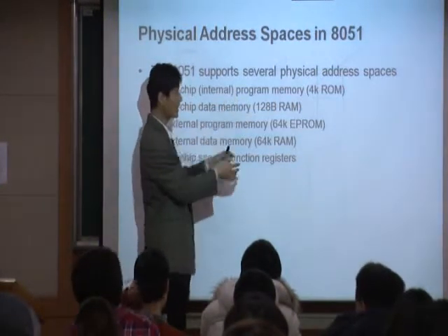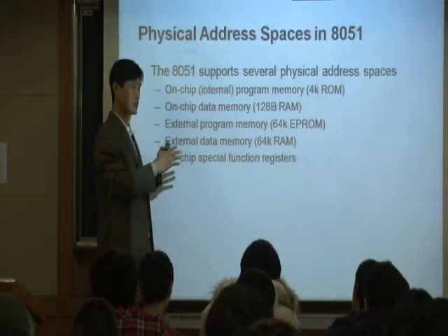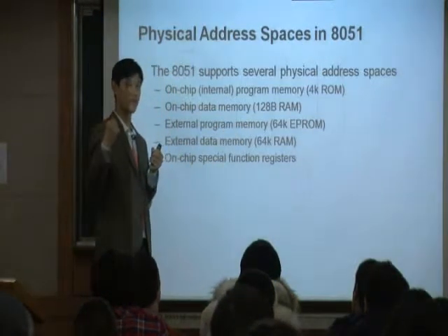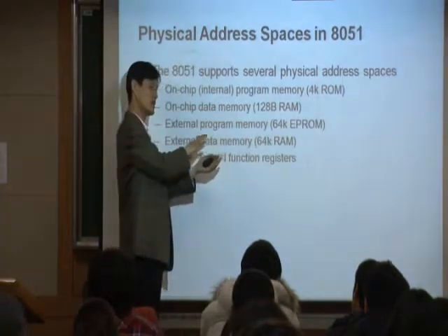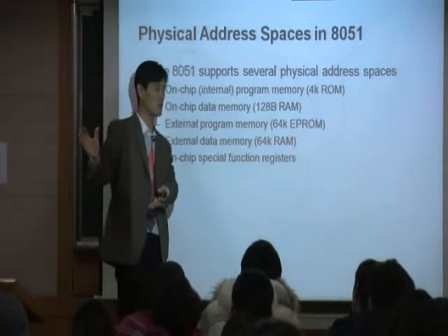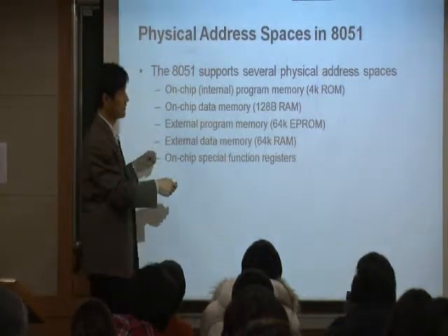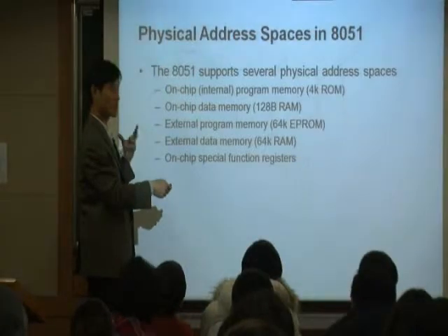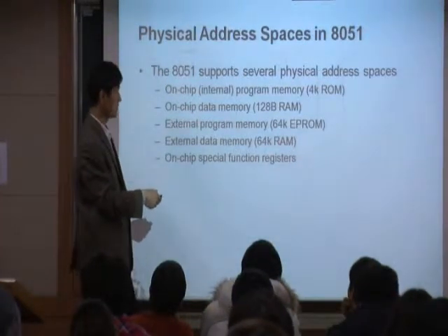So that's data memory space. What you can also do is that you can buy another 64K ROM and put that together here also, right? Then you can also use 100% of code memory address space. Okay, so we have instruction memory 64K address space. We have data memory 64K address space.